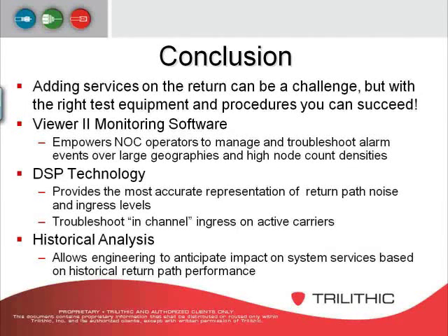DSP technology provides the most accurate representation of return path noise and ingress levels. Troubleshoot in-channel ingress on active carriers. So if you have your modem carriers that are right there, you want to see what's happening up under that modem carrier, because that's what's going to impact that upstream modem carrier. And then also the ability of having historical analysis. This allows engineering to anticipate impact on system services based on historical return path performances.